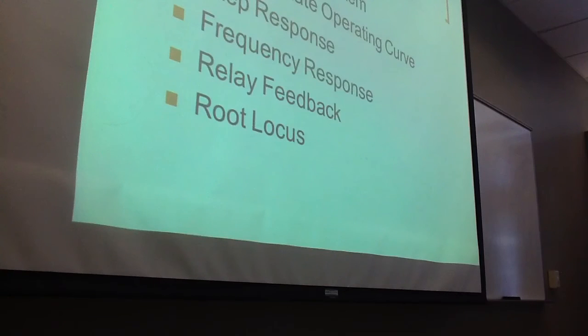So we talked about the spray booth system, how our inputs and our outputs worked, and that both dampers were closed. We talked about the steady-state operating curve and how we use that to set our relay feedback. We talked about step response and the results from the step response, the frequency response, and the locus. We also discussed how changing the set point, the floor and ceiling adjusted our outcome, our output.